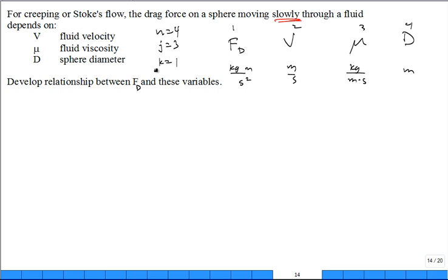All right. So if it's a whopping 1, what do you want to build it around? Build it around the drag force. So pi 1 will start with F of D. And you can put your units down here. Kilogram meter per second squared. Okay, I'm going to divide by mu. That's a kilogram meter second. True?